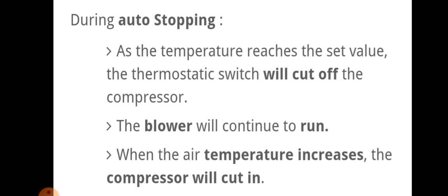During auto stopping, as temperature reaches the set value, the thermostatic switch will cut off the compressor, then the blower will continue to run. When the air temperature increases, the compressor will cut in.